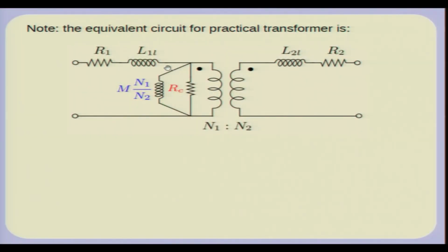And if that is the case, you can actually find out the current which flows. This current here is maybe quite negligible. As I said, the open circuit currents are generally very small. So, what you are going to see is practically R1 and L1 and the referred value of R2 and L2 coming onto the primary side. So, just to draw this. When you do a short circuit test, actually what comes is practically this.